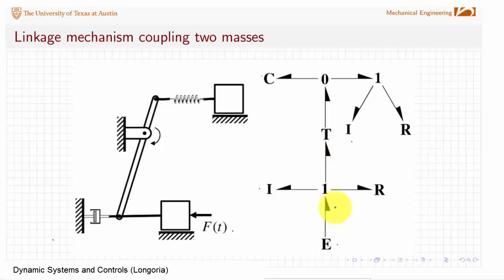Let's start off again with our input force. At one junction, I'm free to go anywhere. I've got to apply causality to my energy storage elements. Let's go ahead and just continue here. Now I've specified the flow at that one junction. Those are efforts. That flow now going into the T means the flow is coming out into the zero, which again does not constrain any of the other bonds yet, so I can apply integral causality on that C, which now does apply that effort source on that zero, which means this bond has to be flow in to the zero.